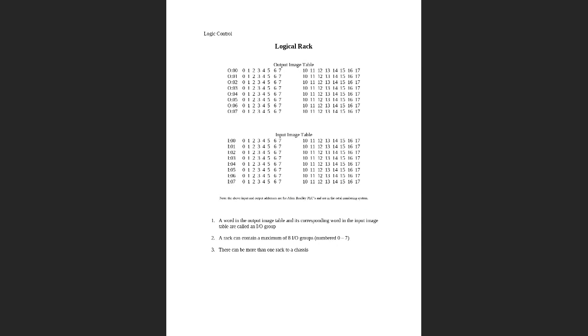What I can do is uniquely locate a slot, and all I need is two pieces of information. Say I want to locate this slot right here. That is in row 2 of an output module, and these numbers actually represent bit positions. The numbers represent the slots I asked you to imagine, and what you would put in those slots is a 1 or a 0.